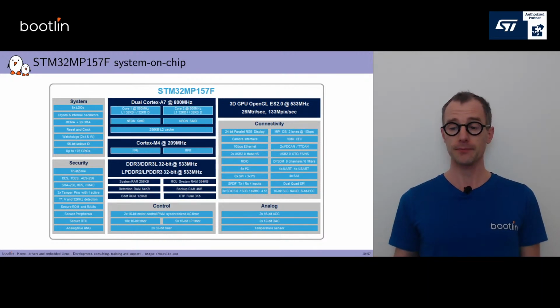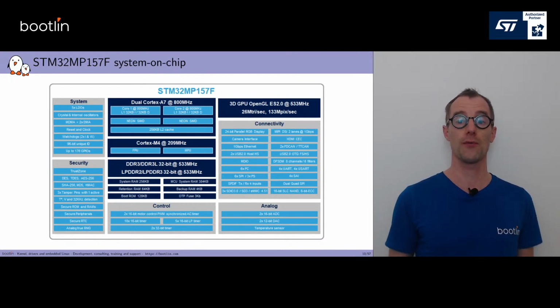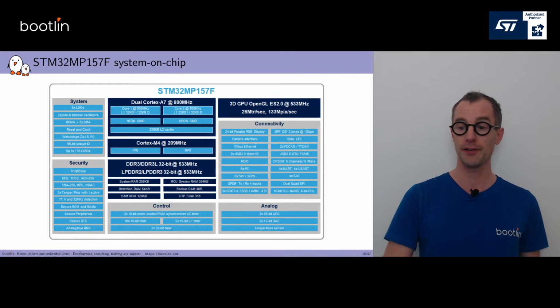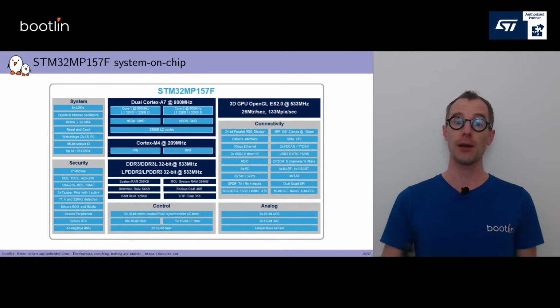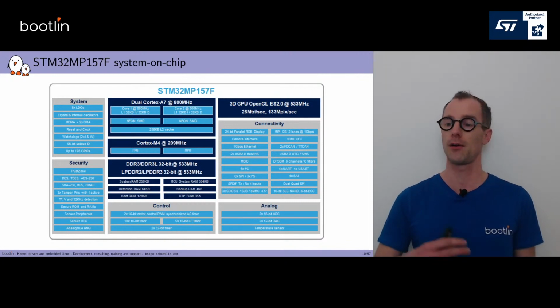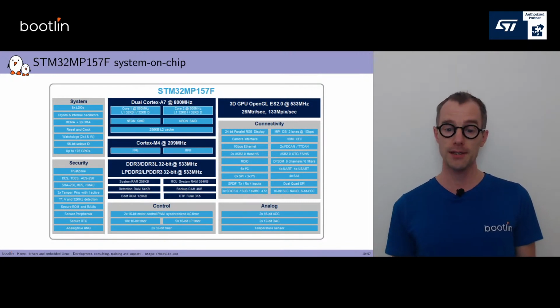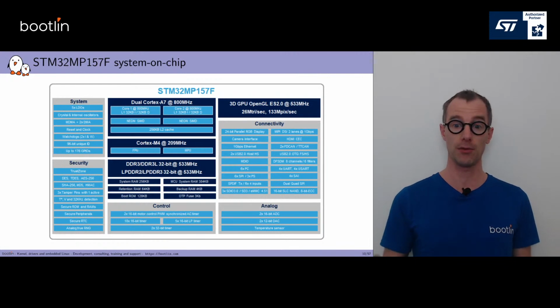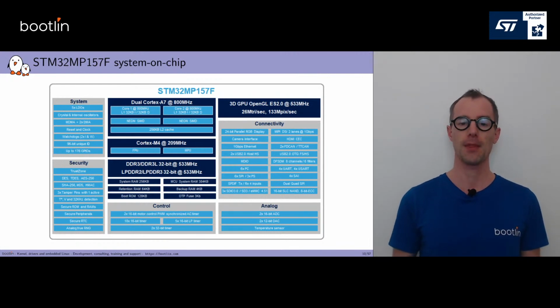It has a GPU. It has a wide range of IP blocks for connectivity: for display over RGB interface or DSI, a camera interface, gigabit Ethernet, HDMI, CAN, SPI, I2C, MMC, and audio interfaces, ADCs, DACs, PWM, and security features. So plenty of functionality available in this SoC.